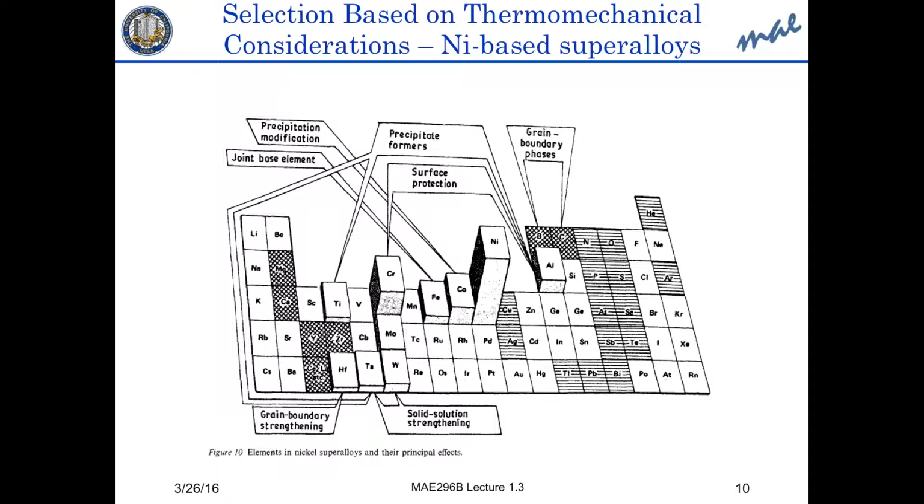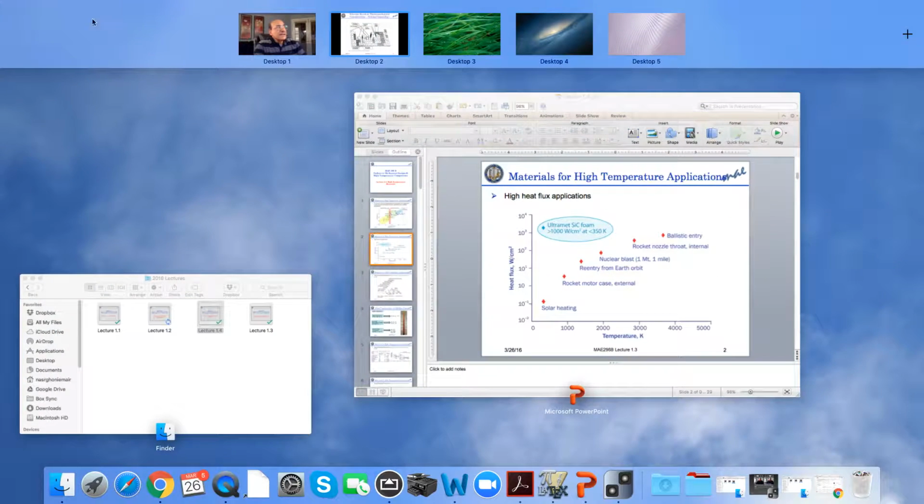Now I will switch next to the next class of alloy systems, the nickel alloy systems, that have very interesting capabilities. Even though the nickel melts at a temperature less than the iron, for instance, iron is 1500 C, and the nickel will be 100 degrees lower. But the nickel itself is a face-centered cubic material. It has good ductility, therefore.